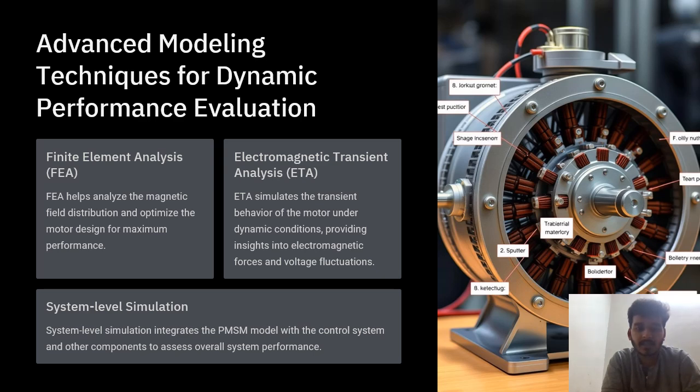Electromagnetic transient analysis simulates the electrical transient behavior of the motor under dynamic conditions, providing insight into electromagnetic forces, voltage and current fluctuations. System level simulation integrates the PMSM model with the control system and their components to assess overall system performance.